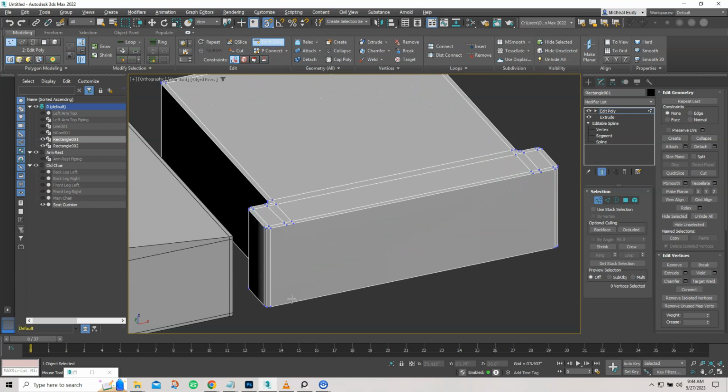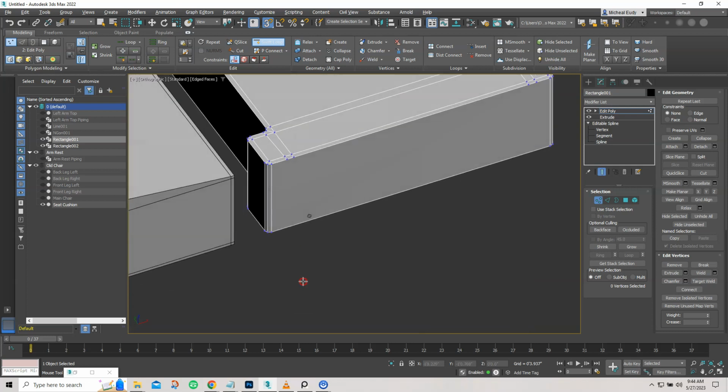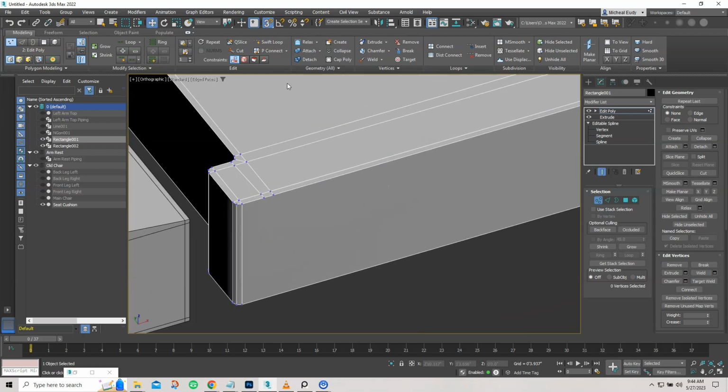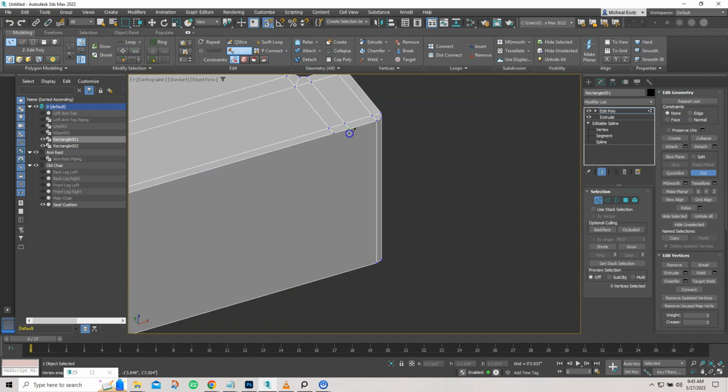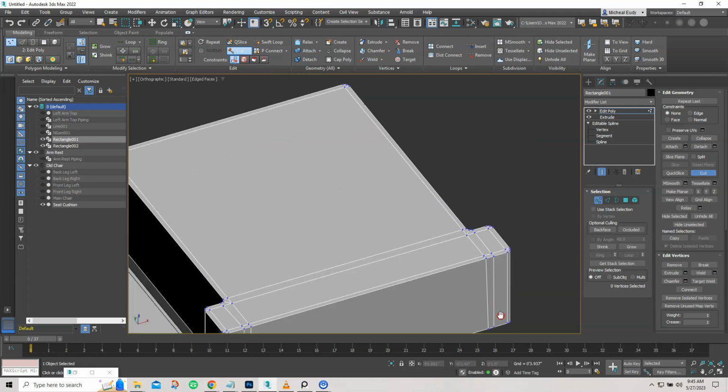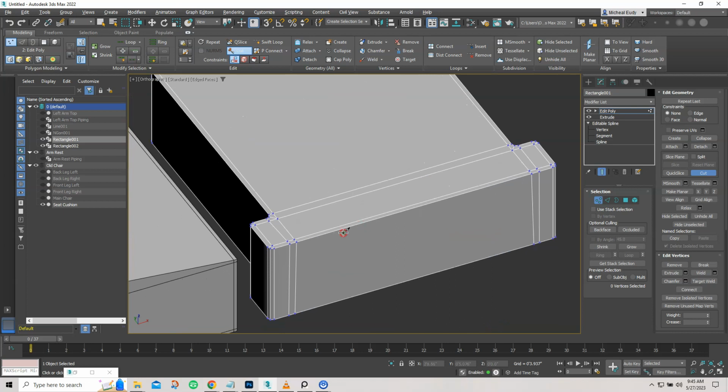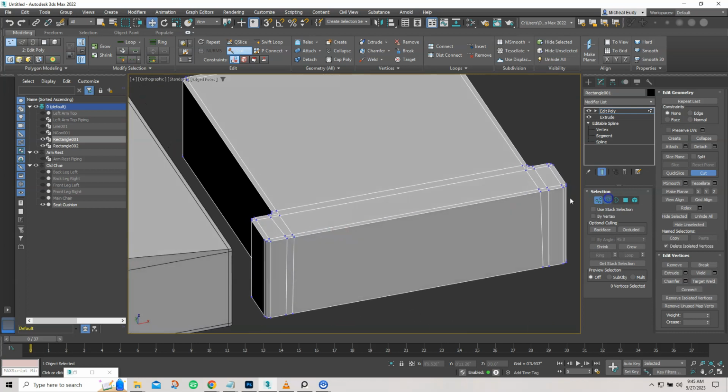So let's just put us... All right, we need to cut these down. I don't need to do the bottom because we're going to put a symmetry on it, so I just got to get the top right. Okay, be sure and turn that snap off. The S key turns your snap on and off, so I have it on when I'm at the top and off when I'm on the bottom. Okay. All right, that's quads.